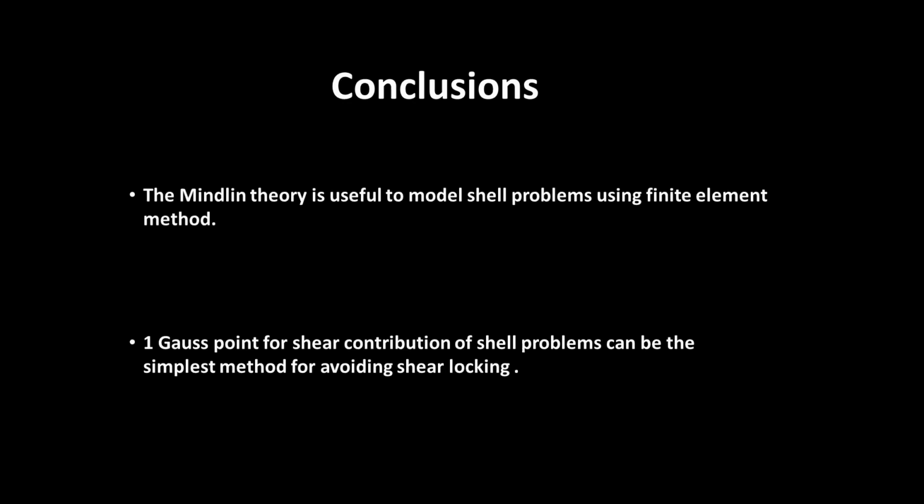From the conclusions, what did we learn? The Mindlin theory is useful to model shear problems using the finite element method. One Gauss point for the shear contribution can be the simplest method for avoiding shear locking.